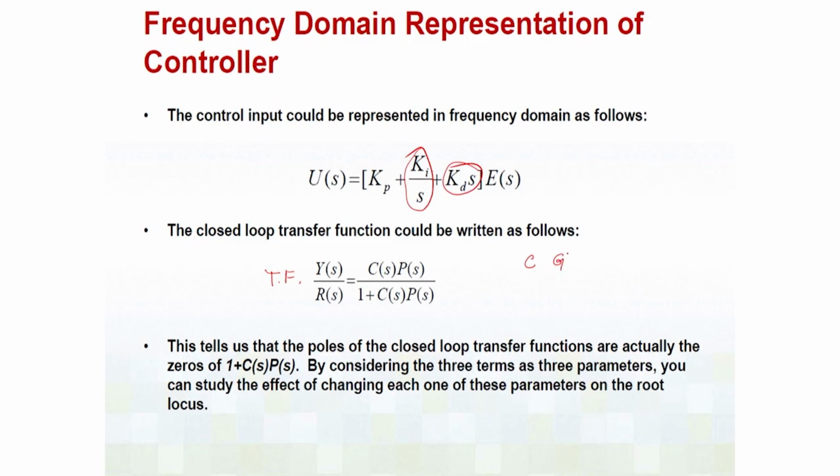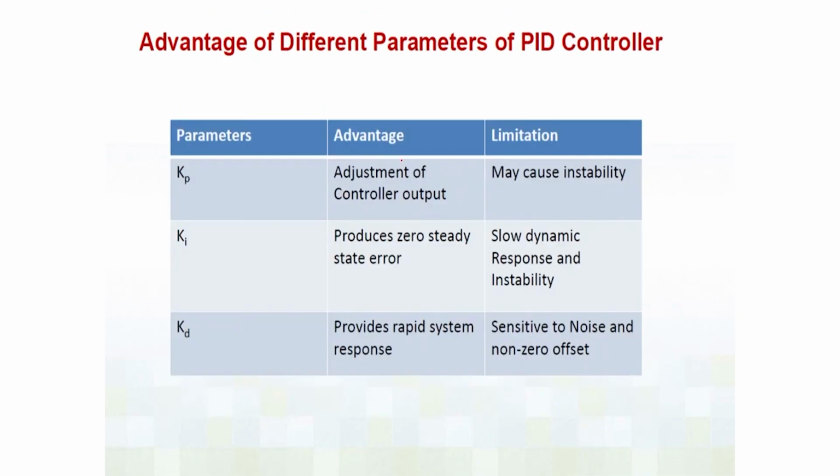This is corresponding to, of course, unity gain in the system, and then over R(s). So, this will become C(s)G(s) over 1 plus C(s)G(s). Something like that will come up. Now, this is the transfer function of the system, where for C(s) I can use the one that we already know.